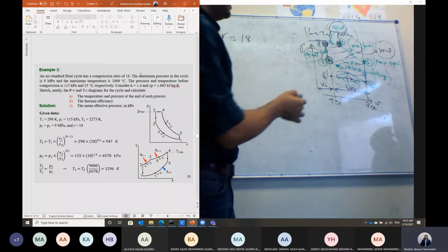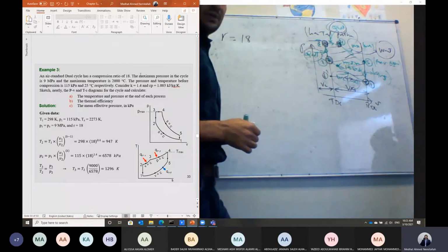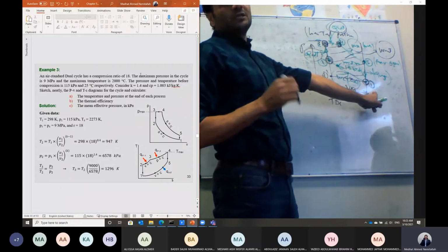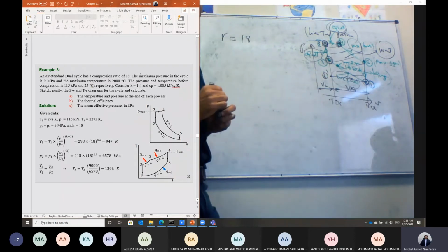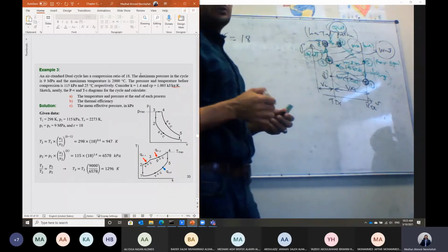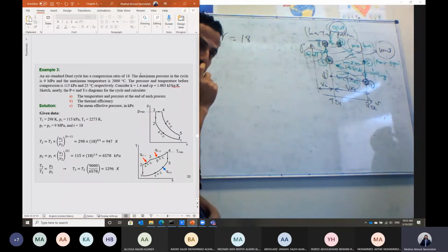And the condition at the beginning of the compression stroke, which is almost the intake manifold condition, intake manifold pressure and intake manifold temperature, is very close to the atmospheric condition at point 1 in the case of a naturally aspirated engine. But in the case of a turbocharged or supercharged engine, the pressure at point 1 should be higher, because we use a compressor in order to raise the pressure of the air, in order to introduce more air to the system.